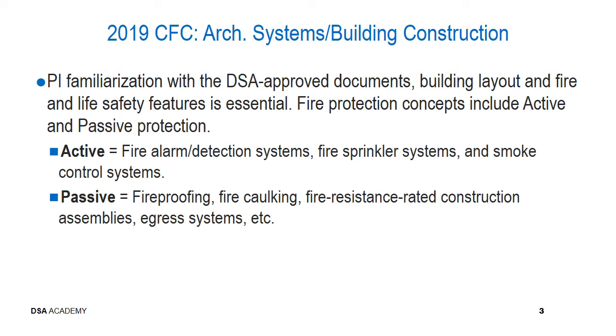Please review inspection card sections 3, 4, 5, and 8. Also, inspection manual sections 3.3.4 for smoke control systems, 3.3.5 for fire-rated assemblies, 3.3.6 for fireproofing of structural members, and 3.3.7 for concealed spaces. Pay special attention to construction assemblies and make sure that the construction of such assemblies does not deviate from DSA-approved construction documents or manufacturer's listed details.